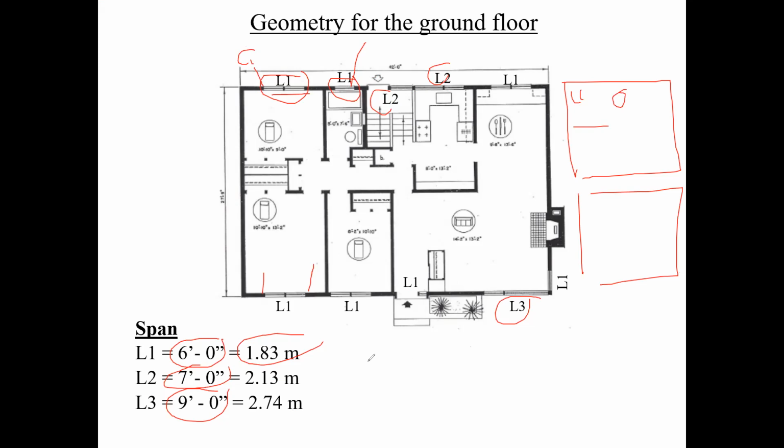So for example, when I'm doing my drawing, the best thing to do is you don't draw a built-up column in your drawing. You simply draw a box and you draw an X across it. That shows that it's a column. And then you can call it C1 and have a schedule. C1 is 3 2x6s, whatever, or you can specify right here on the drawing what these are. And you can't put typical because they won't be typical all around. So it's up to you. When we get to the drawings, I'll show you different options you have to annotate how these columns are going to be on your plan view for the ground floor.